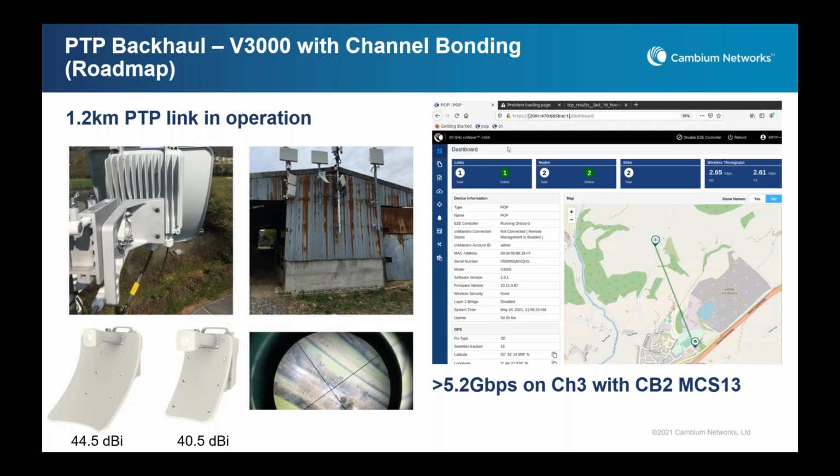And the other nice thing I haven't really talked about is that 60 gigahertz is such a narrow beam and it's a relatively short range of propagation, there's much less concern about interference than you see in other bands. So the interference, the noise floor is lower, and the fact that your signal doesn't propagate as far actually works in your favor for self-interference.